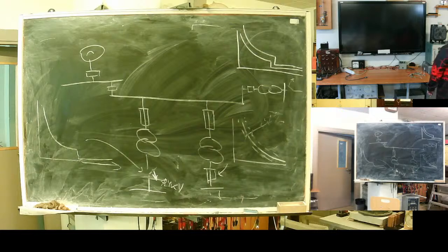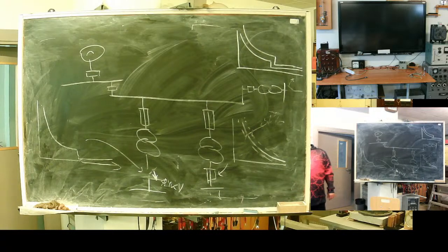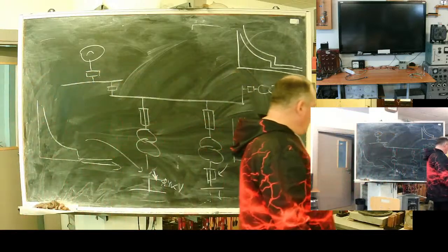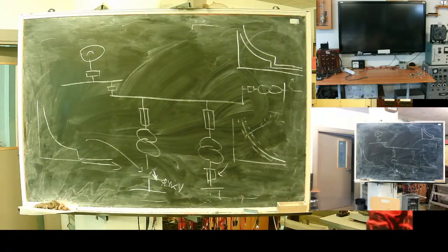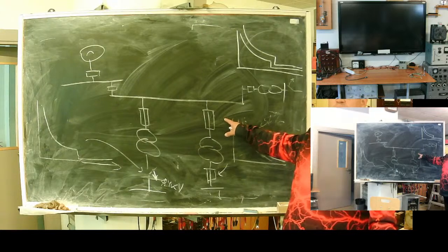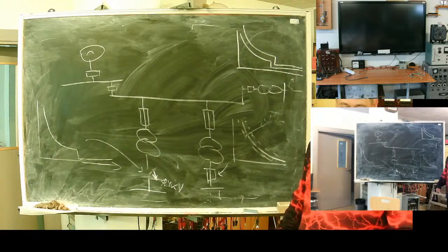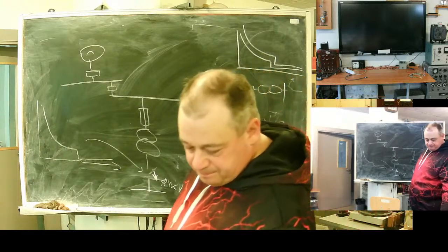In time, such a fuse can suck in humidity inside. Can take water in. This means that during the fault it will operate, but it operates with delay. That's why I'm not pointing an arrow on this fuse. These fuses are not reliable. Believe me. More of that. Also, experience.